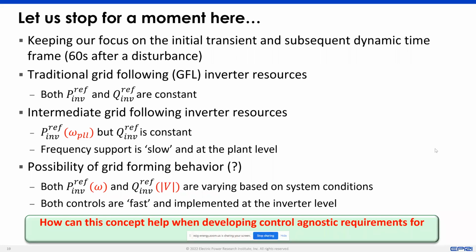The dependency of frequency to load change in an all inverter system is still a topic of research, because we don't know whether it will hold the same connotation, the same behavior in a 100% inverter system as opposed to a machine system. So in a machine system, the rotational frequency of the machine links to the electrical frequency of the network, and then it links to, let's say, the load, right? And then when you have a change in disturbance, you have a flux change and so on.